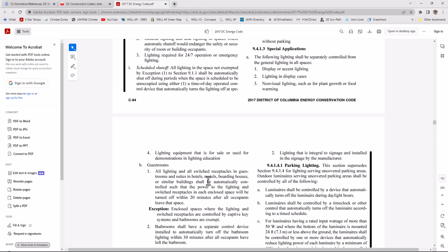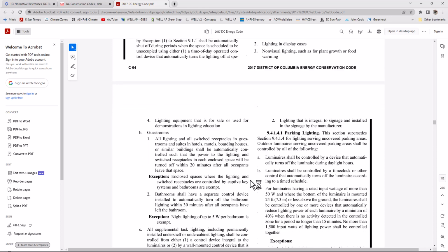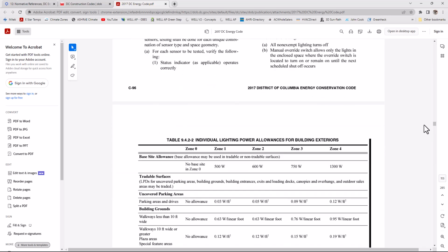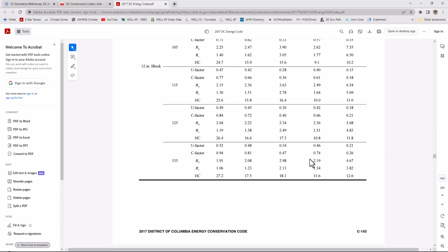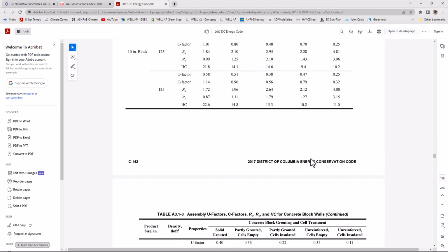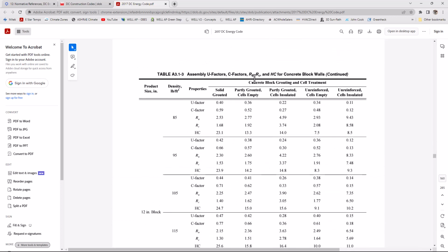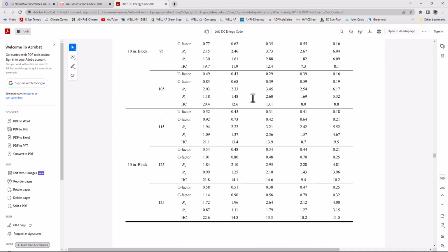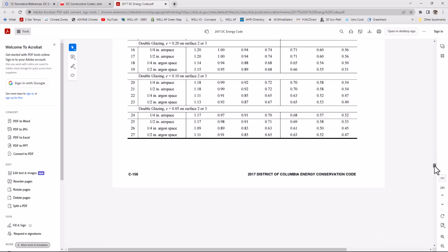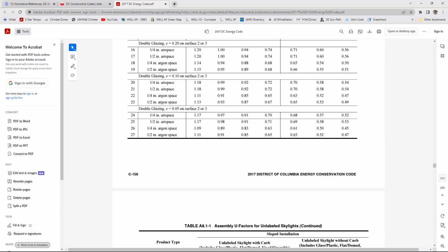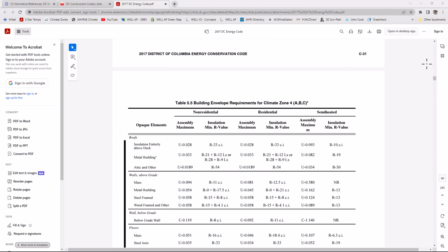So what we do is we go to the applicable code by location, and then we use this energy conservation code to establish minimum insulation values by location and climate zones. As you can see in here, properties, U factors, C factors. And there is a very interesting table in specific. Let me double check. Yeah, I was trying to find it. So it's actually in C31, C32.